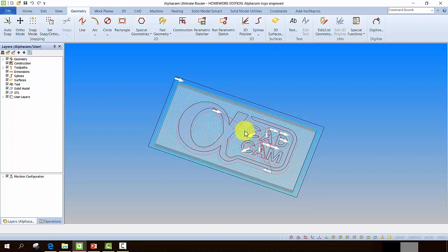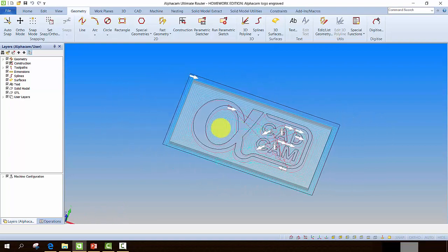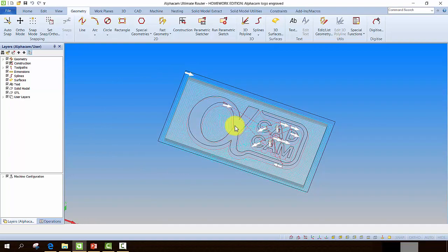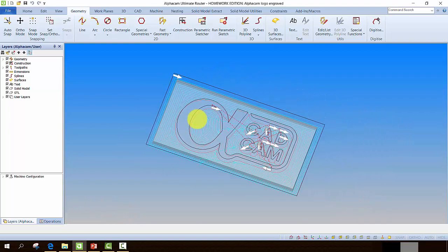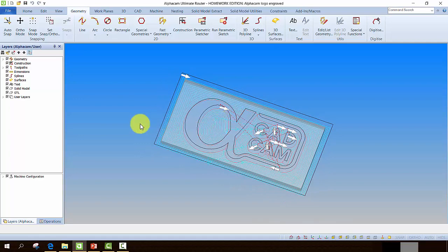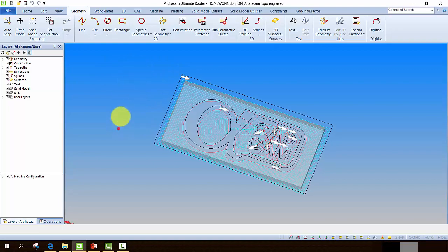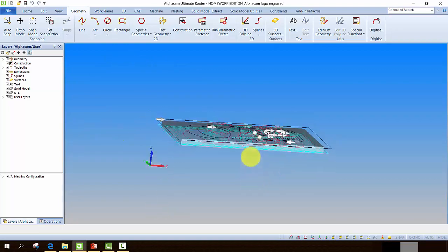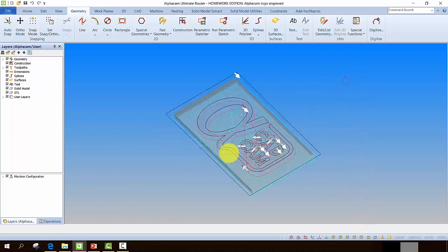So in terms of navigation, to pan left and right, you simply depress the mouse wheel. Those of you with knowledge of Inventor, you'll find that's the exact same command that is used in Inventor. So you depress the mouse wheel. It's not one of the regular left or right click buttons, it's actually the button integrated into the scroll wheel on the mouse. To rotate, it's just a regular left click somewhere in the background. You don't use the same system as you use in Inventor. You simply click and drag a blank area of the screen, allowing you to rotate it as you see fit.